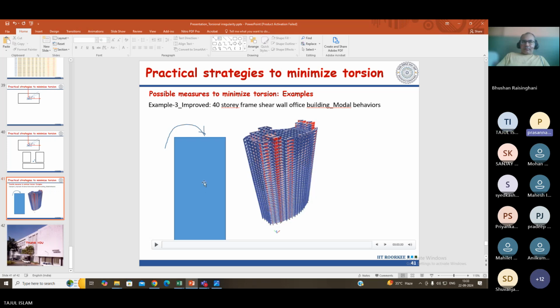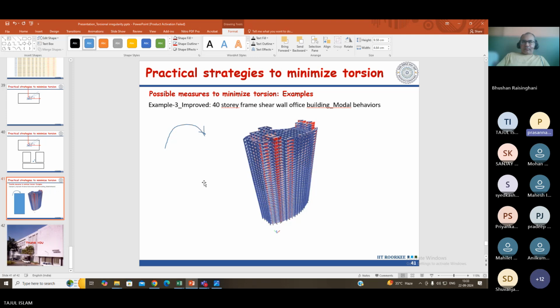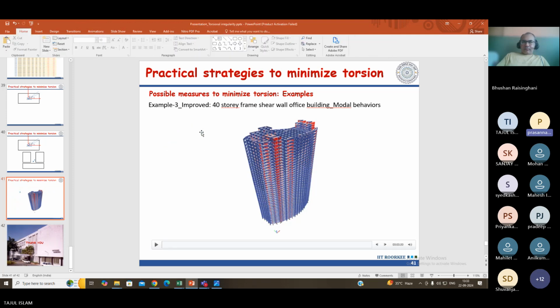Okay, but if I take output forces from the wall, it will give moments, shear, and torsion. If you are telling that moments are created in the walls due to torsion, and shear is also created in the wall, then why should torsion come in the analysis? Whatever the torsion of 100 kN, it is already converted into analysis moment. You are telling additional moment and additional shear, correct? Yes.